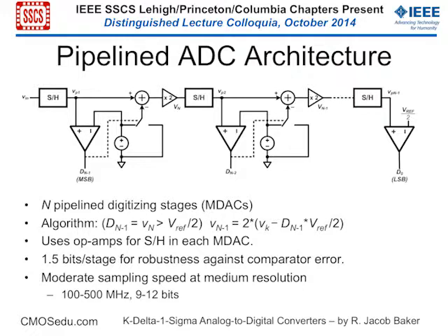Just real quickly, you get a sample and hold. Is it above or below, say, the reference voltage over 2? If it's below, you just pass it to the next stage with the multiplication by 2. If it's above, you subtract VREF over 2, your reference voltage over 2, and move to the next stage. You basically get out a code corresponding to your input, and I'm not showing the latency here to make sure all the words sync up. The nice thing here is after a latency of n bits, you get your word coming out at the same rate you get with the flash.